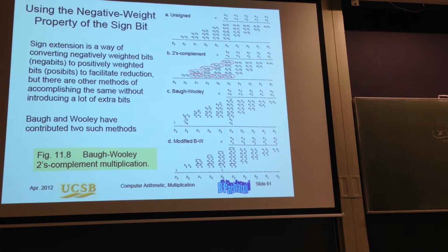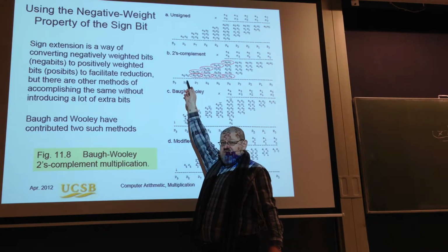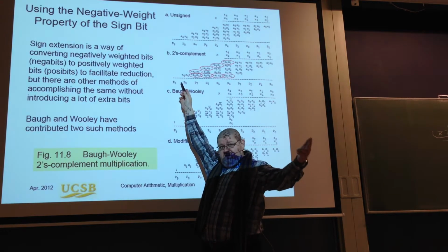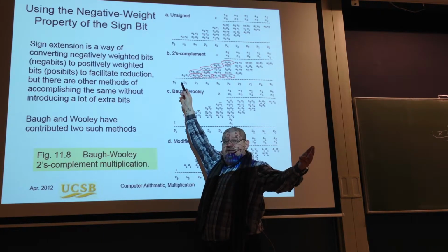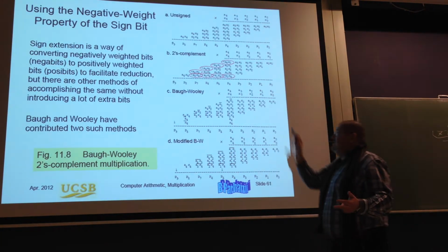And then what I have to do is I have to take into consideration the contribution of those positions in the proper way. Okay? This one in here is not negative, because this is a product of two most significant bits, which both have negative weight. Then this gives me a positive one. But the rest are negative.